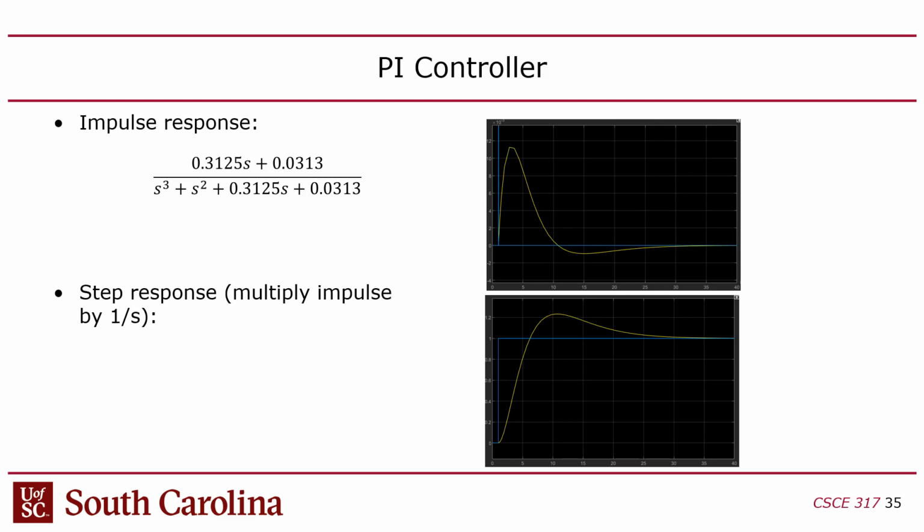The output, the response, is where the coin actually is, right? So what's happening here is that I'm telling the robot, don't move the coin. All right, move it 1 meter. And the robot is moving it up very slowly, but then he overshoots. And he's like, oh, sorry, and he has to go back, right? He had a little bit too much gusto. Moved it too far, and then he had to correct himself. So that's called the overshoot. And this is called the rise time, how fast he got it to the set point.